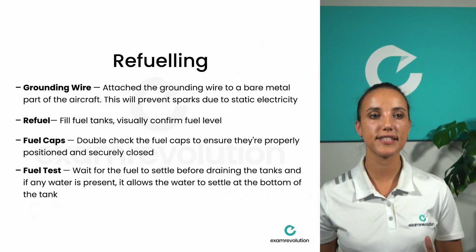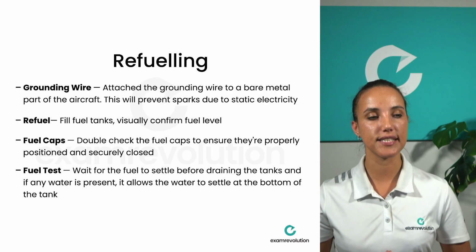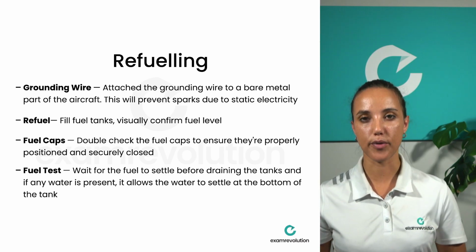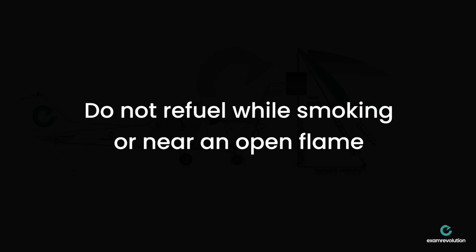Then wait for the fuel to settle if you have time before draining the tanks, and if any water is present, it allows the water to settle at the bottom of the tank. So if you allow the fuel to stand for 10 to 20 minutes, the water should settle in the lowest part of the tank, which you can drain and see if there were any contaminants in that fuel. Do not refuel while smoking or near an open flame.